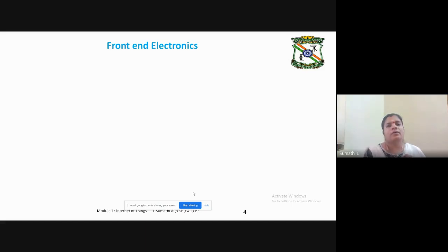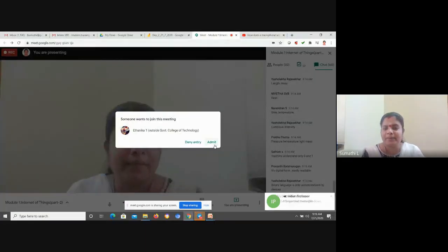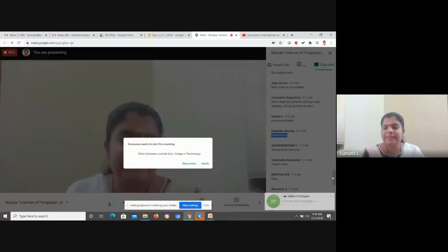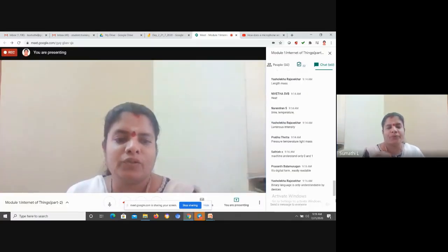Okay. Can I amplify it directly? What will happen if I amplify it directly? In general, you will have noise in your signal. So if I amplify it directly, the noise will also get amplified. So I filter the noise, then I amplify the signal. What is amplification? Amplification is nothing but increasing the strength of your signal, right?